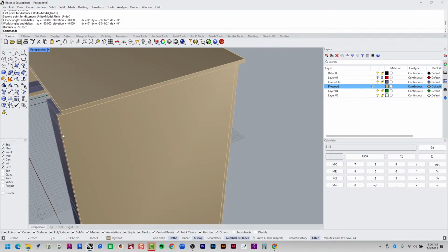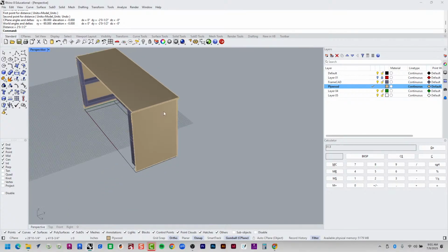So the frame CAD component of this project, the structural component, the overall width of the structural stuff is 2 feet by 6 feet. Plus I have plywood on top of that. So I have to add another ½ inch on left and right sides and another ½ inch on the front side. Does that make sense? Does that make sense to you guys?